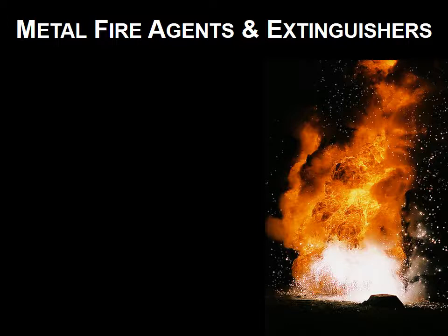For a small amount of burning metal, first cover the fire with powder, then spread a 1 to 2 inch layer of powder nearby. Shovel the burning material onto this layer and apply more powder if needed.